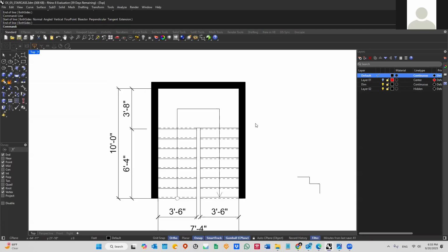As I mentioned before, we are only drawing these walls, exterior and interior, without finishes, right? If we want to add the details and draw these walls with finishes, the thickness has to be changed, right? But for this exercise, I'm just drawing exterior walls at 6 inches.